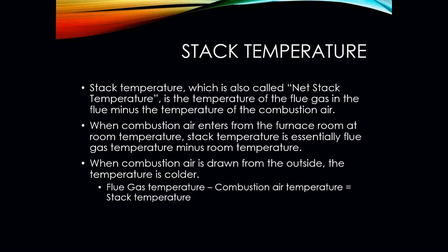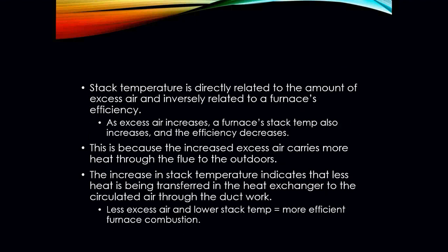So when combustion air enters from the furnace room at room temperature, stack temperature is essentially flue gas temperature minus room temperature. When combustion air is drawn from the outside, the temperature is colder. So flue gas temperature minus your combustion air temperature will give you your stack temperature.